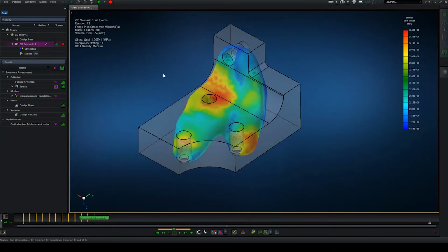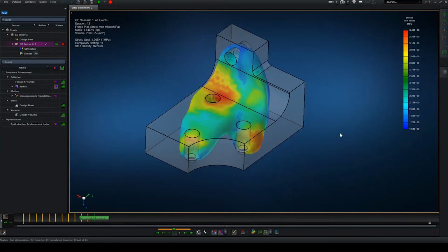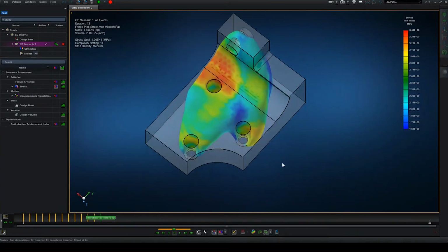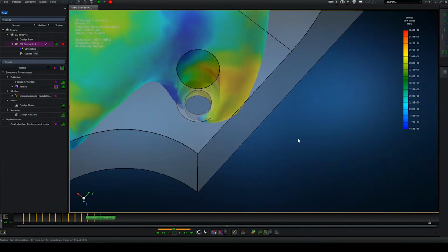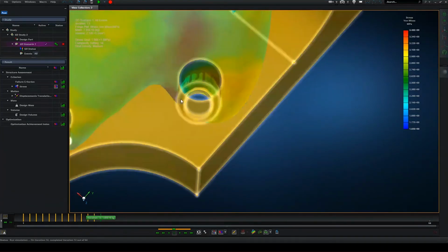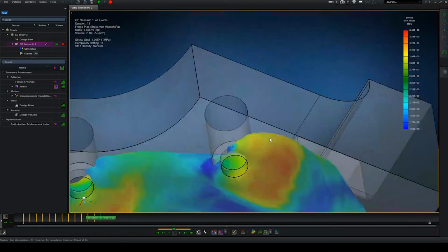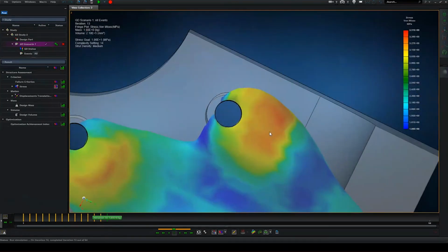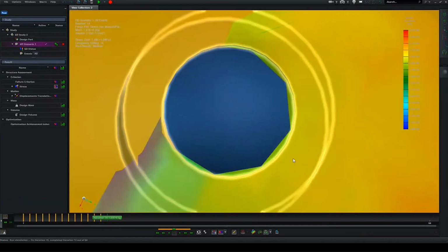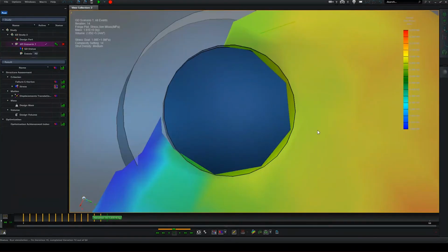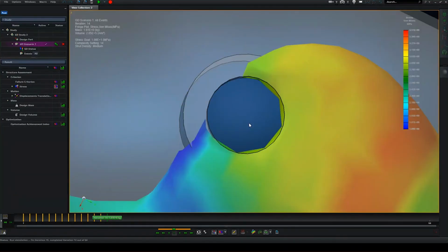Some of the other settings that you, of course, have available that I've mentioned, I haven't employed here, for instance, is the ability to define areas where it has to retain material. So at this stage, I didn't specify that this ring or section of the model has to stay intact.